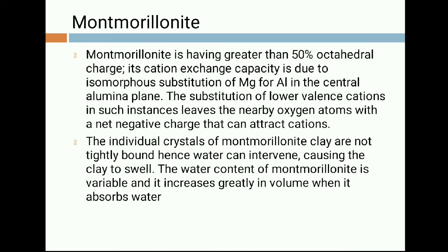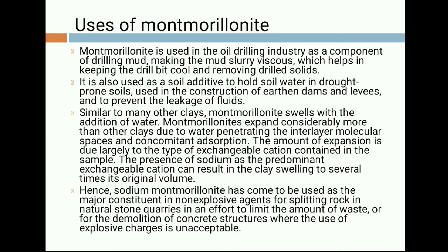The individual crystals of Montmorillonite clay are not tightly bound, hence water can intervene causing the clay to swell. The water content of Montmorillonite is variable and it increases greatly in volume when it absorbs water. The cation exchange capacity of Montmorillonite is very high. Because of that, Montmorillonite has the most swelling property. Out of all the three minerals, that is kaolinite, illite and Montmorillonite, Montmorillonite has the most swelling property. Now let us see what are the different uses of Montmorillonite.